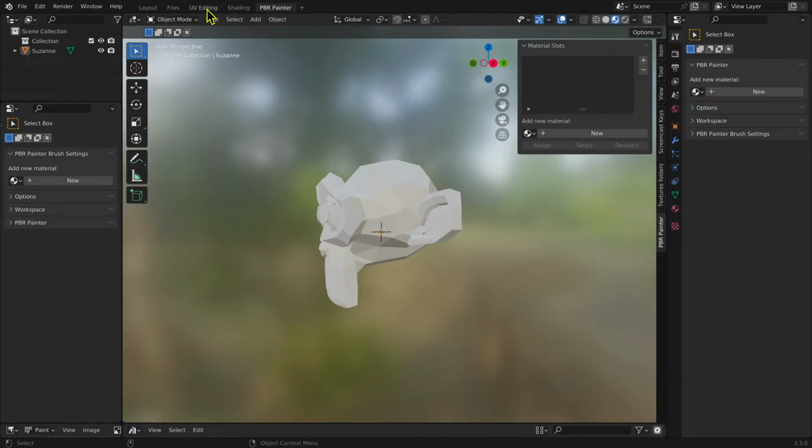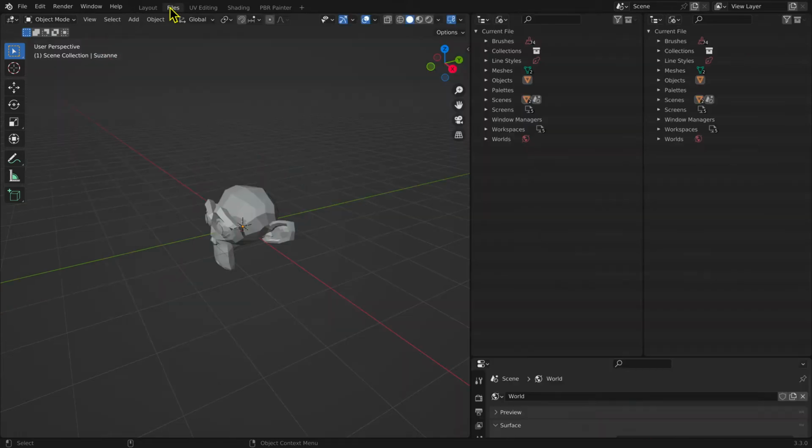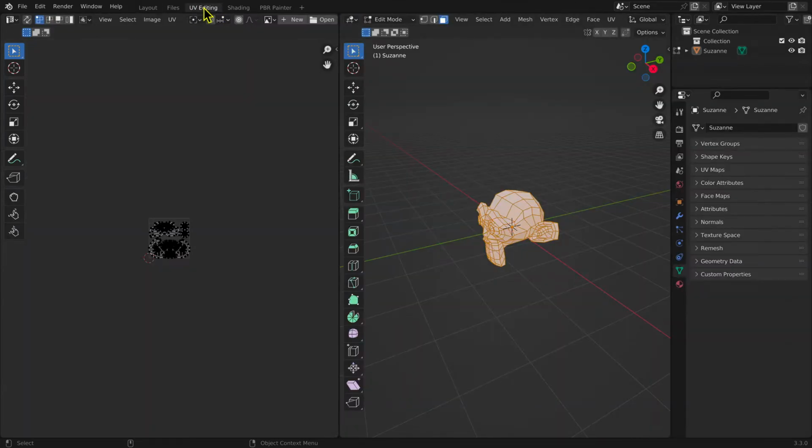While this flexibility can be useful, I find that most of the time I would rather have the same view when I switch between workspaces. Synchronize Workspaces places a button at the right-hand end of the 3D Editor's menu bar, which allows you to synchronize the views.